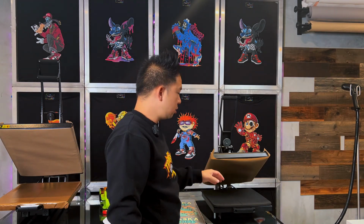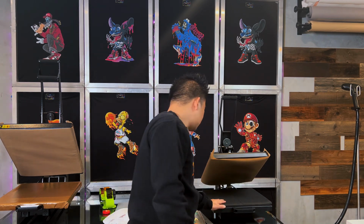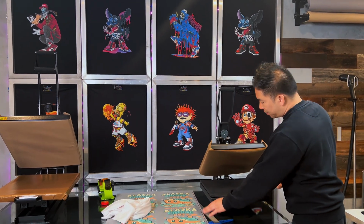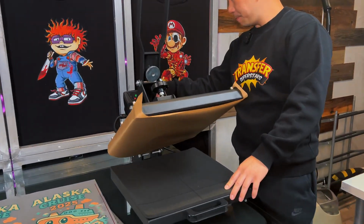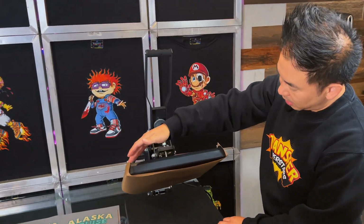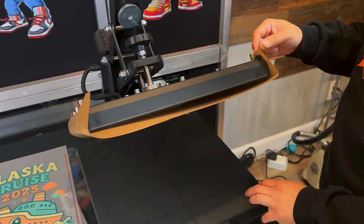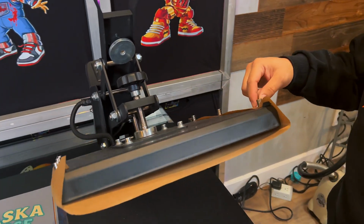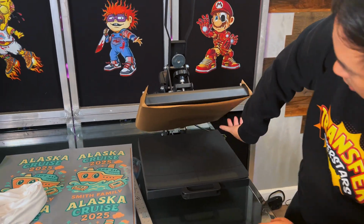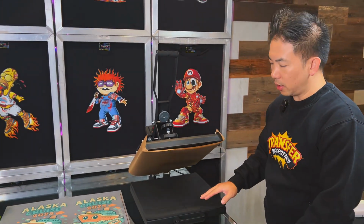And what I'll be using to press is the 15 by 15 clamshell press. This gives enough pressure for DTF and really embeds the DTF into the shirt. So let's fire it up. The other thing we did with this one is modify the top portion by adding a Teflon onto it, just a couple magnets, cheap magnets you can find anywhere. You can probably do the same job with some heat tape and just drape it along the top. So that saves you a step from having to put that Teflon on top of your print every single time.